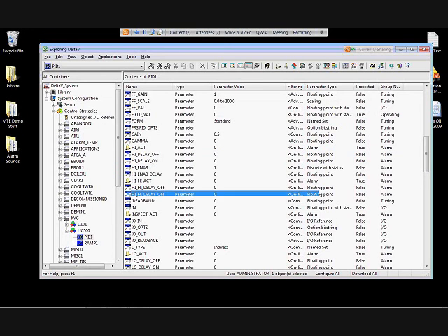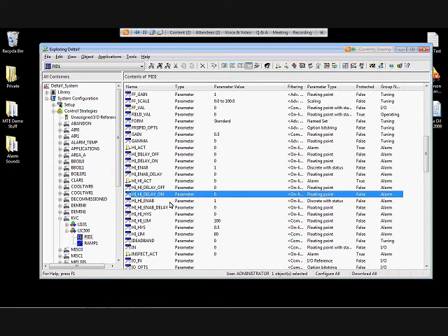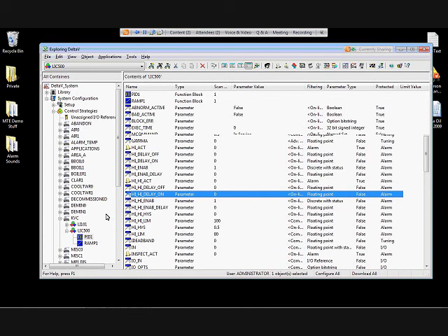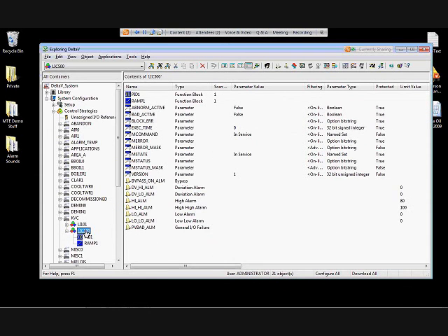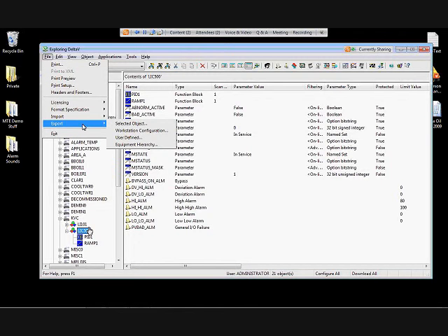So let's go ahead and begin that part of the work process, rationalization, by getting this module's information out of this engineering environment and over into the SILAlarm environment. To do that, I'm going to use a standard feature of DeltaV, which is an export feature using bulk edit. So I have highlighted the particular module I want to export, and I could just as easily have exported the whole area, or for that matter, all the control strategies across the system, but I'm going to be very focused in this demo and highlight there, and do a file, export, user defined.